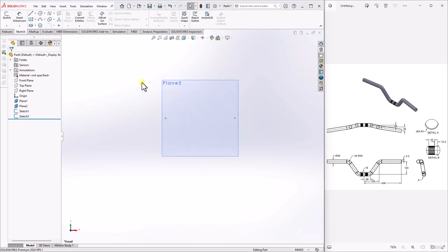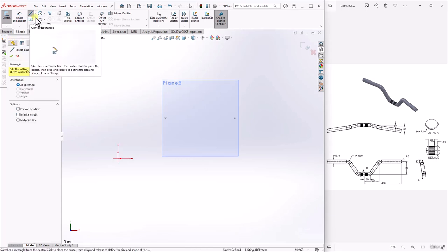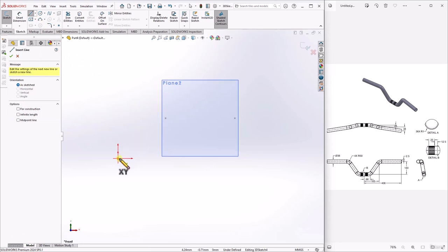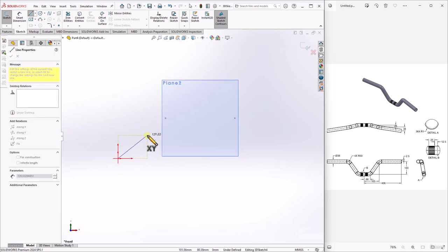After creating the points, we need to invoke the 3D sketching environment to create the path for the sweep feature. From the sketch environment, select the Sketch drop down and select the 3D Sketch button. Now go to the Line drop down and select the Line. Now click on the origin and move the cursor in the positive X direction of the triad and click when a value above the cursor is displayed close to 66 mm.